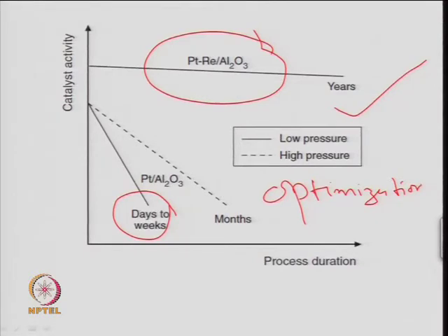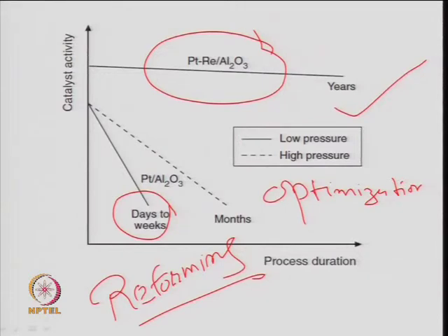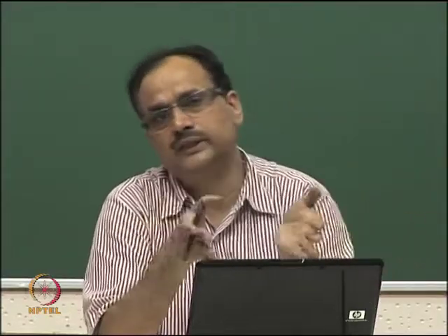So, this is a kind of reforming catalyst which is used for the reforming of naphtha, right. So, reforming of naphtha generally is done to produce more and more aromatic hydrocarbons, right. And the idea is that reformate gasoline is desired as high octane gasoline. So, reformate gasoline is produced by the reforming of this naphtha compound, right. But nowadays you know that high aromatics may not be desired. So, this can be used for blending purposes, right, and to produce aromatics which can be used for the petrochemical industry or specialty chemicals.